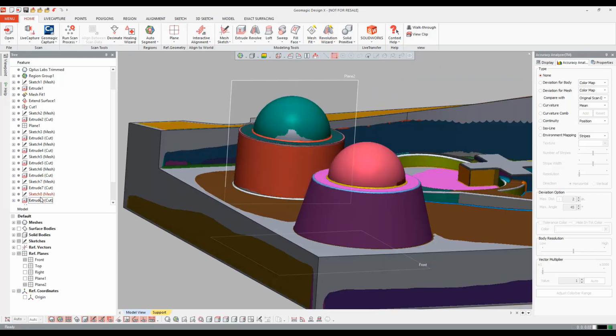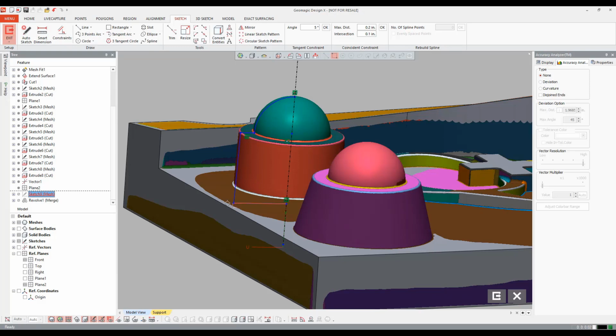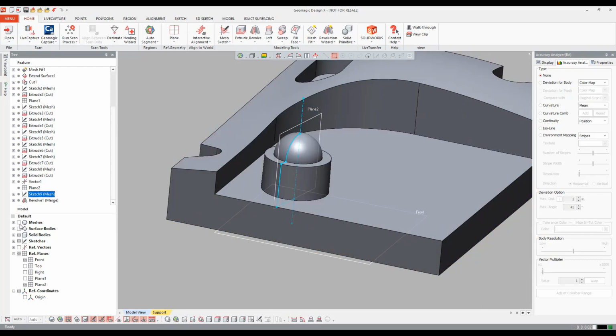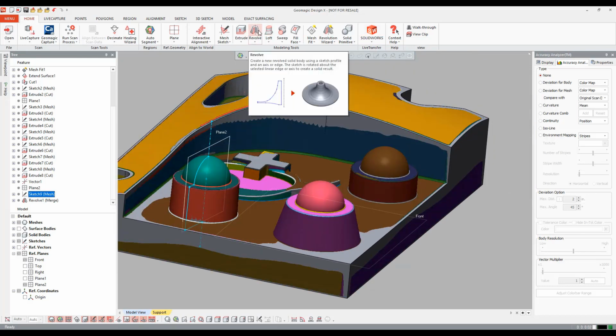So I accept that, but I will have to drag the sketch into the part. So I'll go to Edit Sketch, and I'll just drag this down into the solid. And I'll hit Exit. You can preview the revolve we made. So let's do that to these next two.